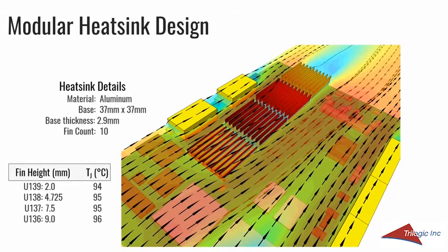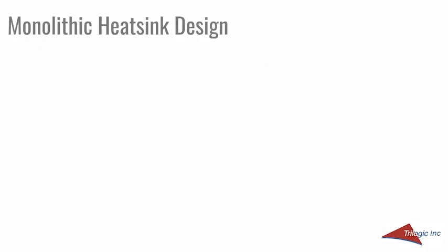So it worked well, but many people pointed out during the webinar and after that monolithic heatsinks are a great choice when trying to maintain components at the same temperature. And I agree, connecting components through conduction is a great way to make the hotter component cooler and the cooler component hotter, bringing them together, and then convect the heat away at the same time. So anyway, it's a good choice.